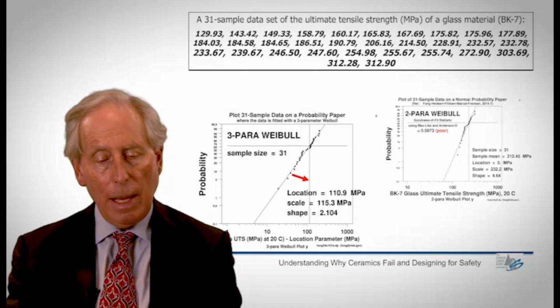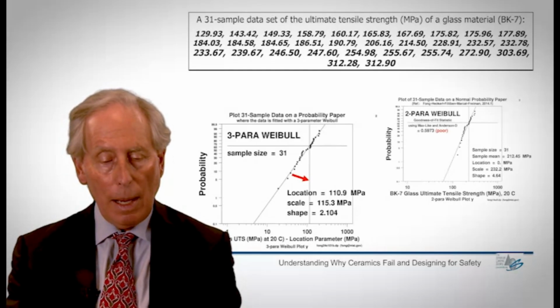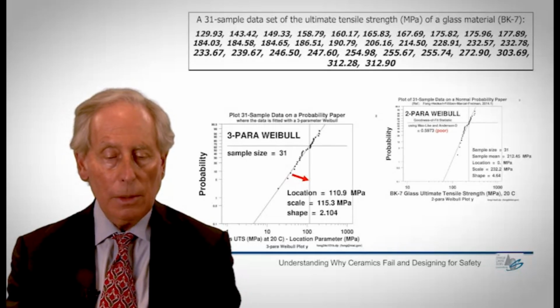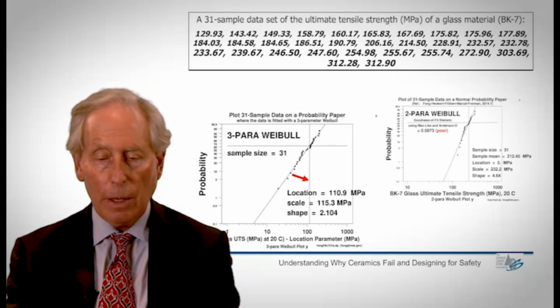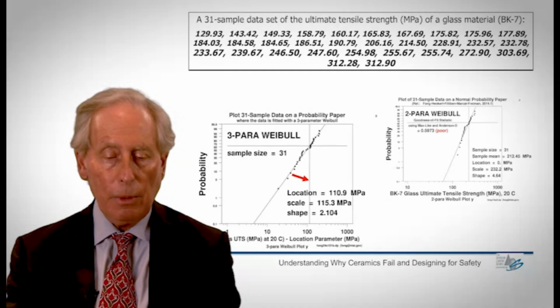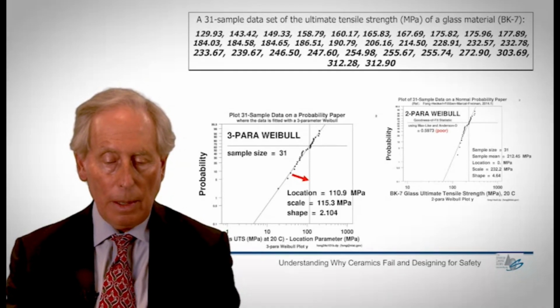One of the points I would make here is that even before a more recent analysis, it was pretty clear. I talked about the difference between 2-parameter Weibull and 3-parameter Weibull, that the 3-parameter Weibull function fit the data a whole lot better than 2-parameter Weibull, and this is the expression we used to determine the statistical distribution of the failure times that we're interested in. And just to illustrate why 3 parameters is almost always better than 2-parameter Weibull.